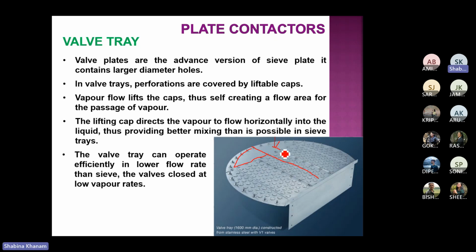Okay, it moves towards this, reverses its direction and then exits from here, right? So in that way we consider the inlet and outlet both are on the same side, number one. Number two, when will this type of flow occur? When I'm having a very low flow rate of liquid.